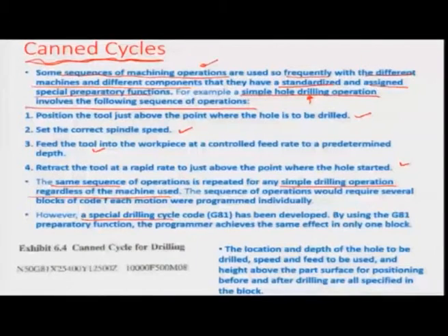So, the sequence would all operate if you design a special drilling cycle, okay, which is of code G81, and let us say in this particular cycle you mention that at a certain command block number, the G81 code exists corresponding to the initial x and y position, and I am taking the same values as the fixed sequential format was describing. Let us say 25.4 mm and 12.5 mm of x and y was the first point over which the drilling was being carried out.